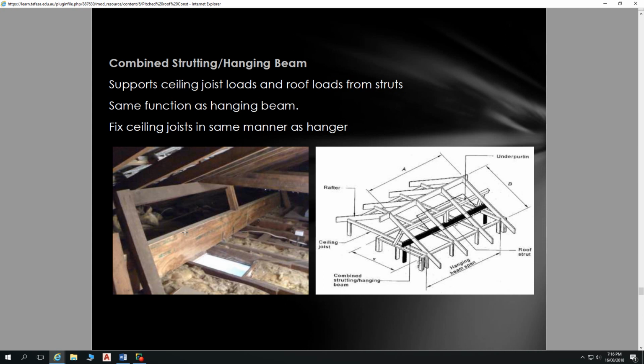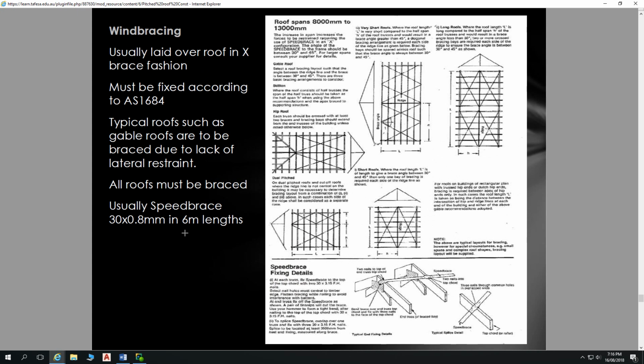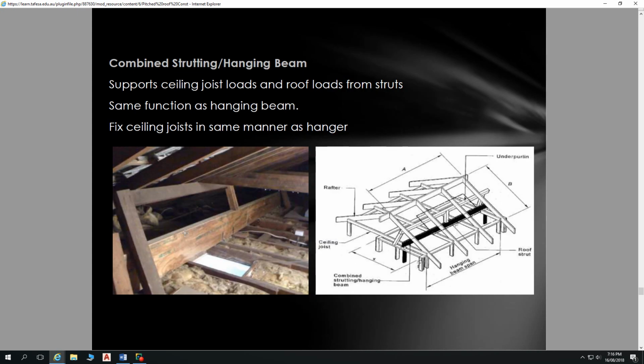Okay. So engineered timber, that's anything whereby we get some pieces of timber and we stick them together in some fashion. Now that might be that we get scrappy logs, chop them all up into lots of little bits, and then make a timber beam out of it. It might be where we take flitches of timber, so really thin pieces of timber, just like plywood, glue them all together and make a fat beam out of that. Now, of course, we don't do that ourselves at home. It all happens in a factory. It's all designed to a certain strength.